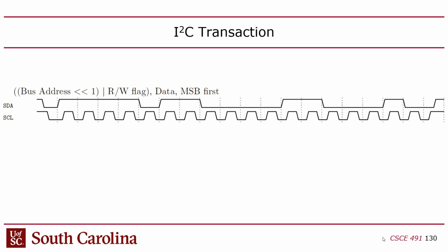One thing that's not consistent, though, I think, is that you can define the behavior of a NACK. You can interpret what a NACK means differently depending on the peripheral. That's one way peripherals can play around with the meaning of what a NACK is.